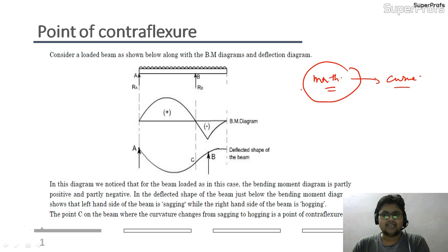I want to remind it again as this is a very important point, and in the GATE paper you can see various questions like this, where they will give you the loading diagram of a beam and ask you to find the number of contraflexure points. They will not ask you directly for the number of points where the bending moment diagram is changing its sign.